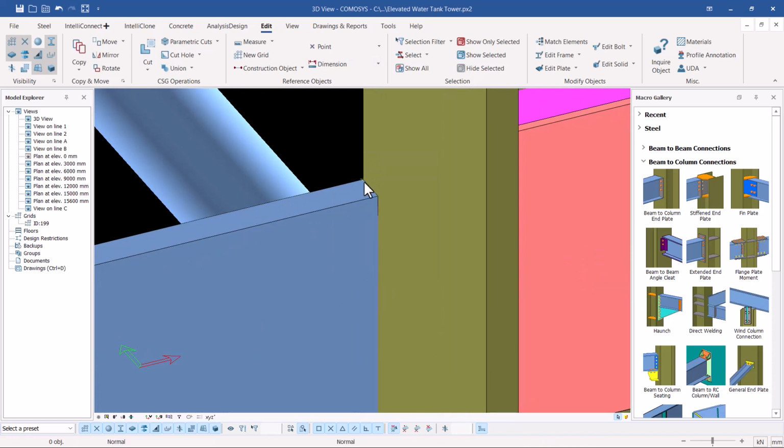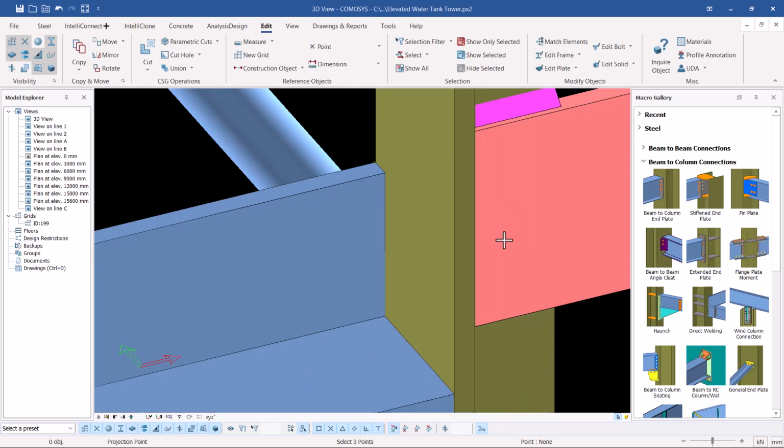So I want to bring this point. I can't just click on that, then try to guess the next point here. Now I want to give you a trick on how to project this point to this location. So once I've selected that point, or just don't select, just come to points and then pick projected point and press Control and just mouse over the edge of this particular member here and snap on that spot, and mouse over the next location and snap on that. Then pick the point that you want to project right there, and if you click on that, you'll be able to see we have our point on that location.